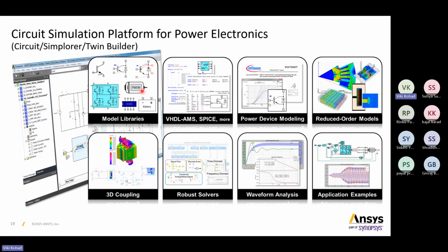The model libraries are also there. Here you can see already designed components like IGBTs, MOSFETs, motor models, battery models, and a three-phase rectifier model. You just need to search for the models you need, extract them, and design the circuit on that basis. The languages are VHDL-AMS, SPICE, and also Python and C. If you want power device modeling, those components are also there. You just open the already designed components and give them the values you need, so it can run by your own strategy.